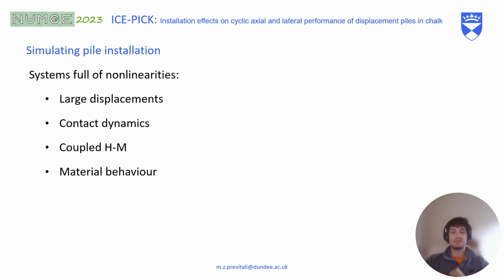So we are simulating the installation procedure. The system is quite complex to simulate because it's full of nonlinearities, such as large displacements, contact dynamics between the pile and the material, coupled hydromechanical behavior, and the chalk behavior itself.